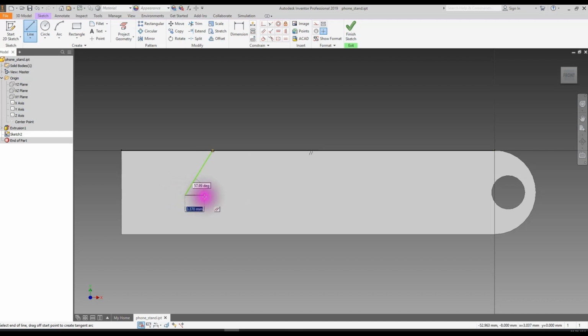Left click. The line tool continues. We just go a little bit of a distance. Now we want it to be perfectly horizontal. Click again, and then go up towards this upper line. And if you notice here, to the left, there are 2 parallel lines showing. You can see here is a little constraint tool and a constraint symbol.